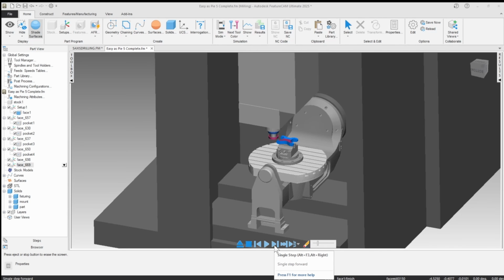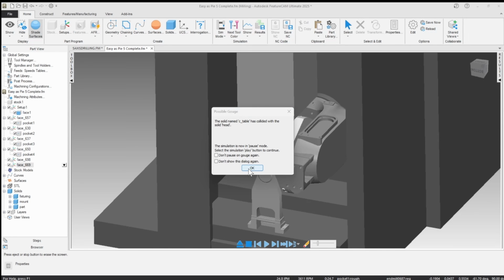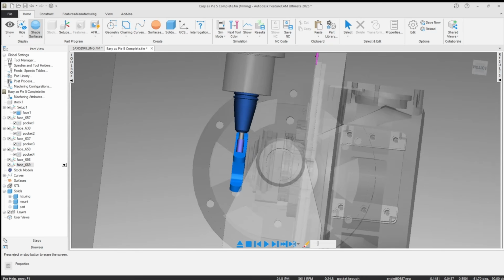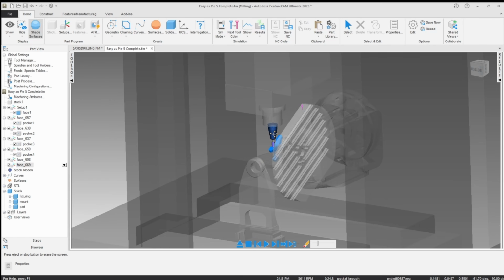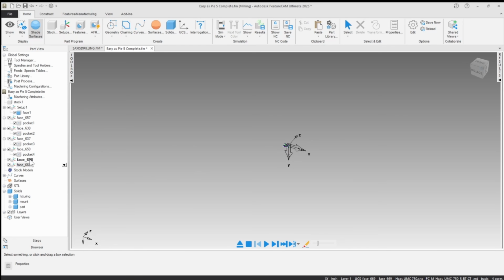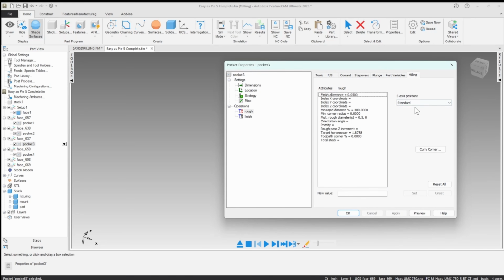I do have the limit thing turned off, but there's our facing. And we rotate, and I have another collision, and it tells me that we're hitting here, so we got to get longer tooling or taller fixtures, right? And then just as a reminder, you can go to any operation, whether it's just a single operation in a feature, and change the positioning rule.